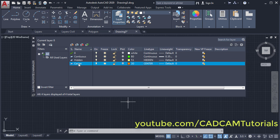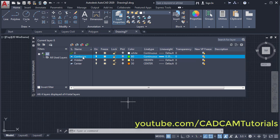If you make any mistake while typing the name of the layer, you can change it. Just select that name and again after some gap click there. So it will go into editing mode and from here you can make any changes you want. And once you have edited the name, click outside. So that name will be changed.